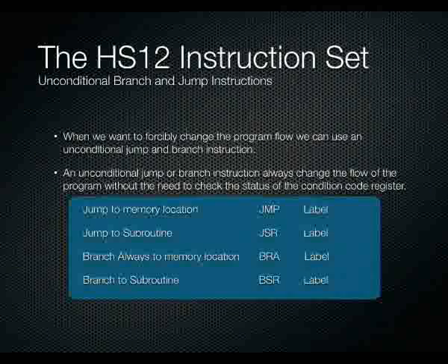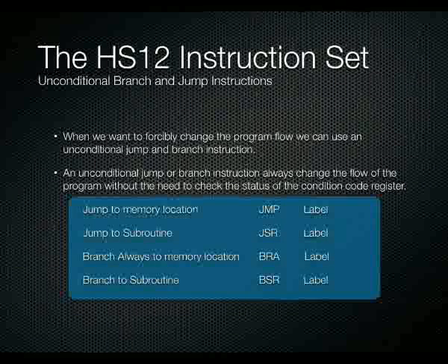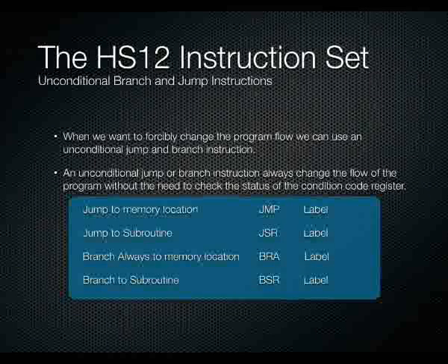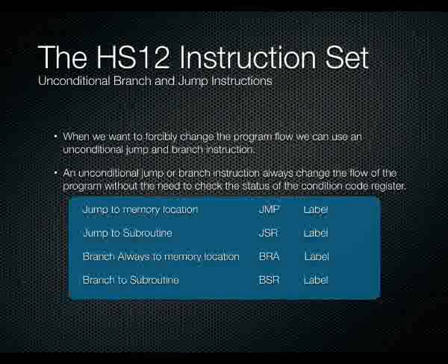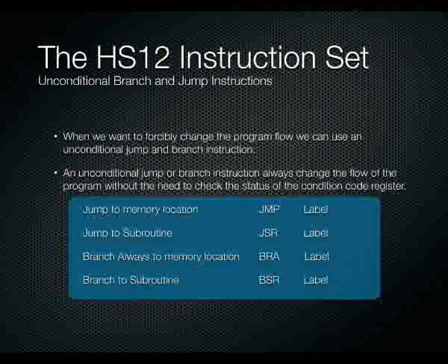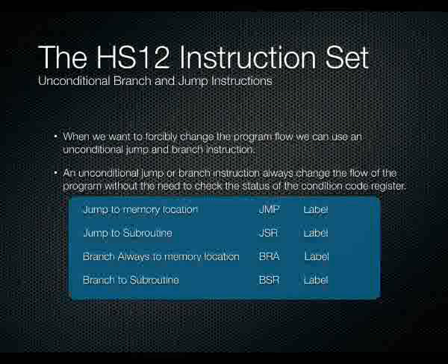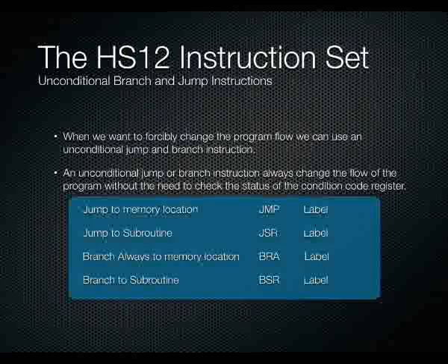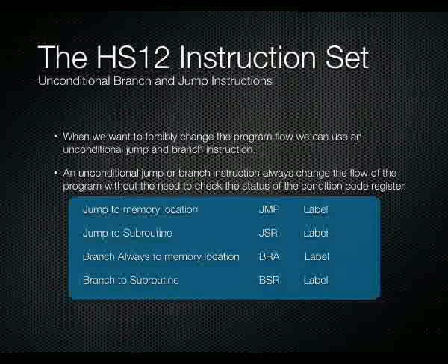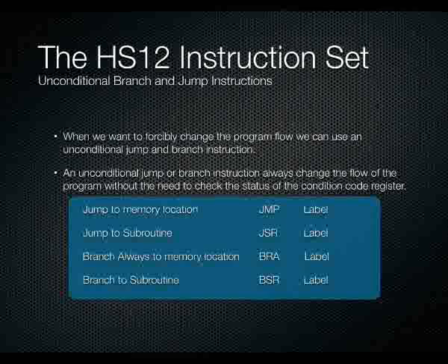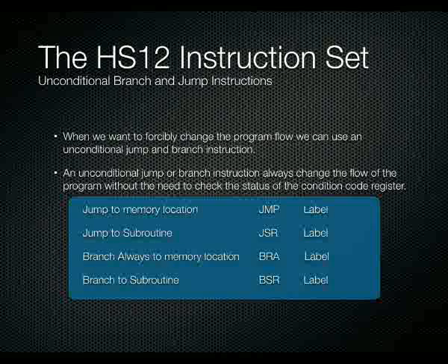Okay, we also have unconditional branching and jump instructions. Unconditional branching is simply when we want to jump somewhere. Irrelevant of what operations have taken place, we simply jump or branch somewhere else inside our code. So these are good for jumping around, if you need to jump to another chunk of code, or jump to a subroutine, or you simply want to branch.